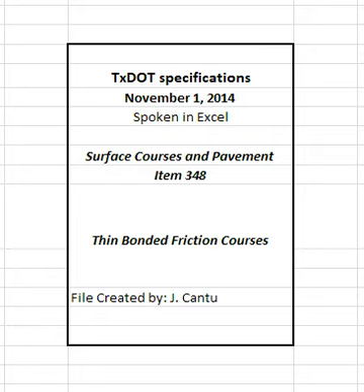The engineer may also obtain independent samples. If obtaining an independent asphalt binder sample, the engineer will split a sample of the asphalt binder with the contractor. The engineer will test at least 1 asphalt binder sample per project to verify compliance with Item 300, Asphalts, Oils, and Emulsions.